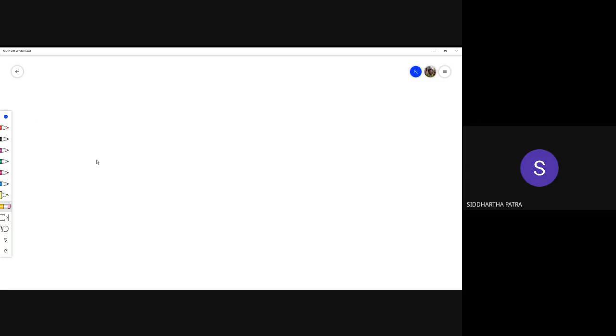That is the expression that we need when we are trying to get the gradient of the N bar vector with respect to the natural coordinates. The individual components are going to be del Ni, del xi j. The number of rows is determined by the number of shape functions, and the number of columns by the number of natural coordinates.